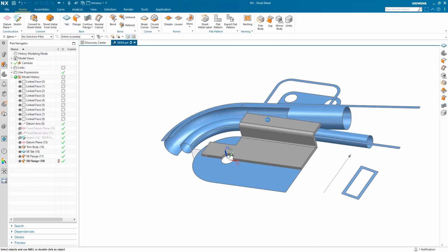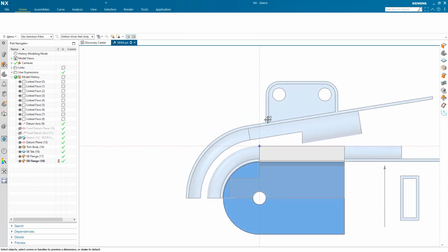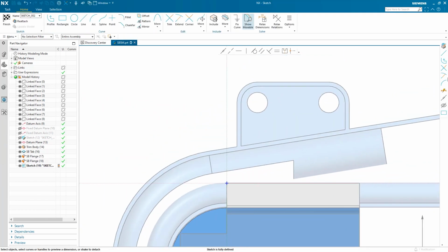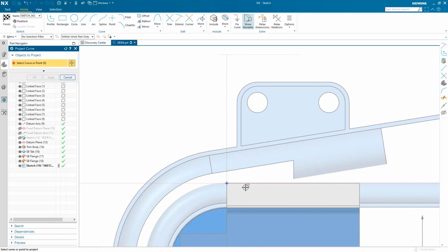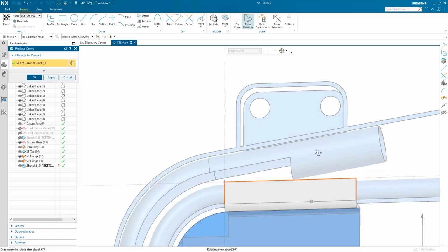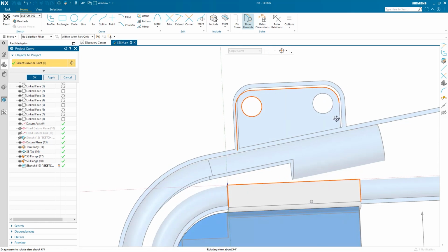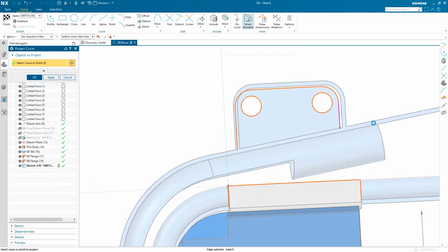Next, we can extend the flange using a secondary tab that will incorporate the fixing holes shown in the reference geometry. I will select the flange we created to make the sketch for the tab. I'll use the project geometry function to reference the existing flange. Then I'll reference the holes and edges of the bracket to fix the bracket to the bike, which will ensure an exact fit into the assembly.